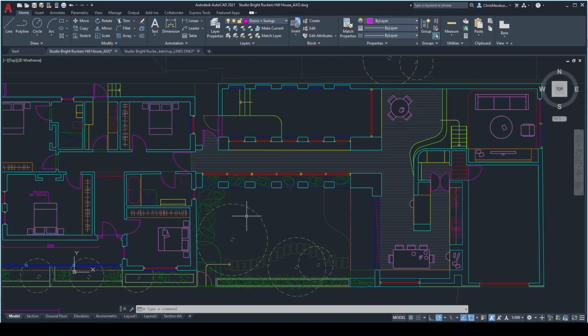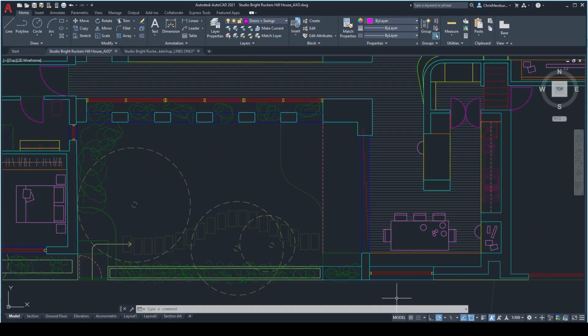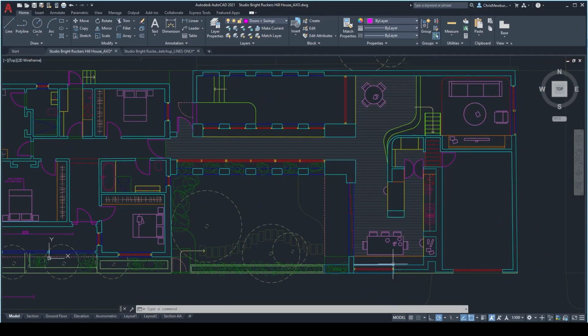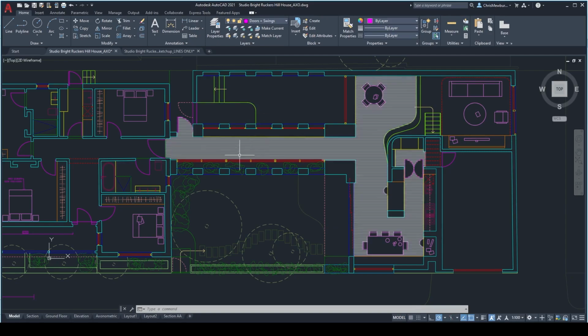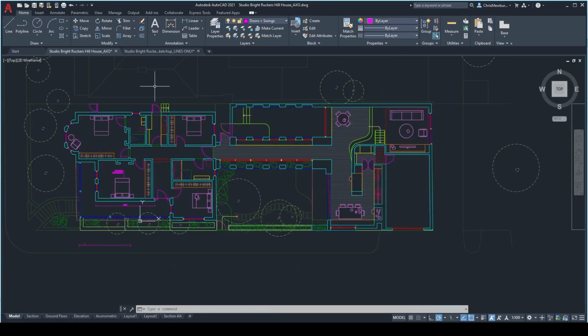They might keep some of that stuff, but everything else really we can just do by using the line tool, using the tape measure tool to connect points in space from one side to the other. So really, unless you've got anything that is a sweeping arc like this, that's going to be a little bit harder to do in SketchUp, I recommend just walls only.